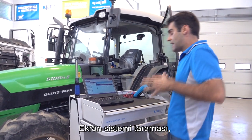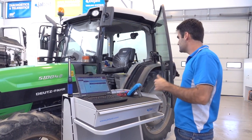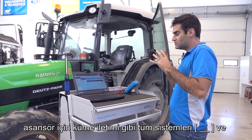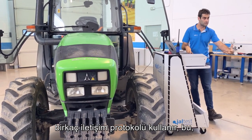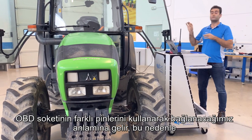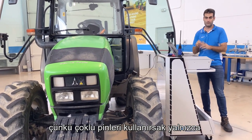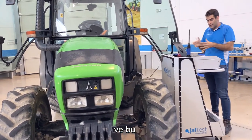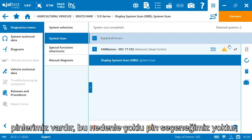Display system scan gathers all of the systems like cluster, transmission, like the elevator for the hitch, and this collection is called display system scan, and it uses several communication protocols. It means that we are going to connect using different pins of the OBD socket. Therefore, we cannot use multi-pins, because if we use multi-pins, we can only have access to one specific system, and this one, it's a certain amount of systems, so we have different pins. That's why we don't have multi-pins option.